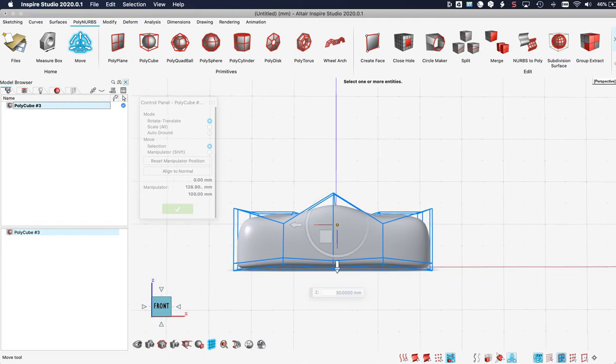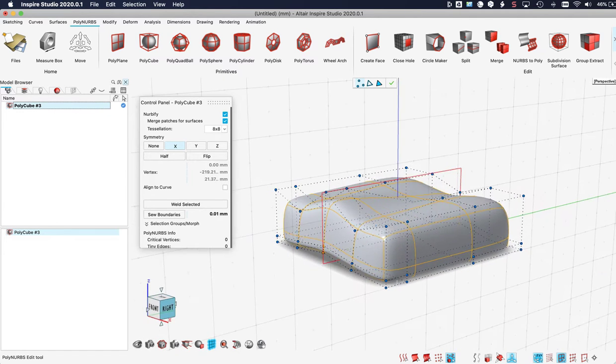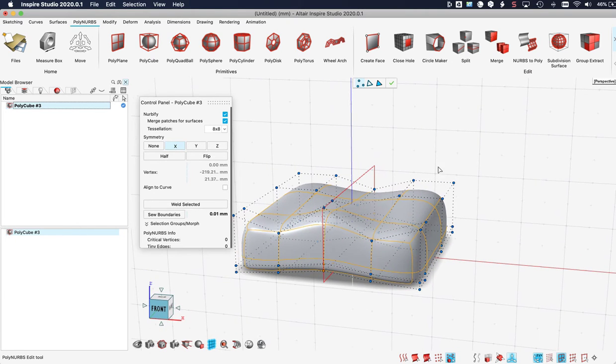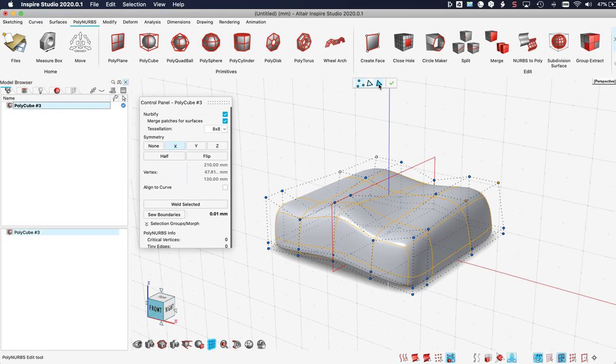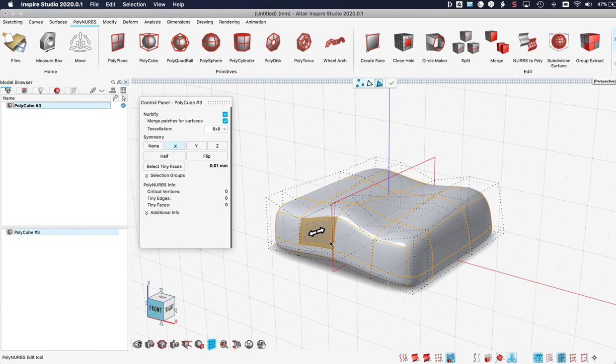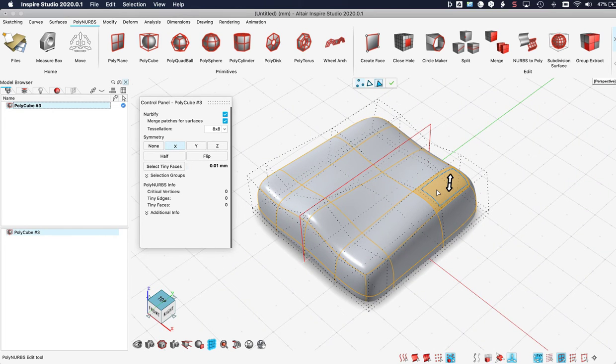So this already is very nice. I'm okay. And let's move a little bit of the points upward. Maybe move these two a little bit more inward. And now let's see what we can do by editing the faces. So I go to the third option, I just stay in the tool, and now when I move my mouse, you see that the faces become active. So let's select this back right face. I click it and the white counterpart will also be moved.